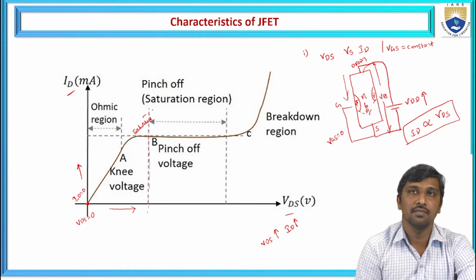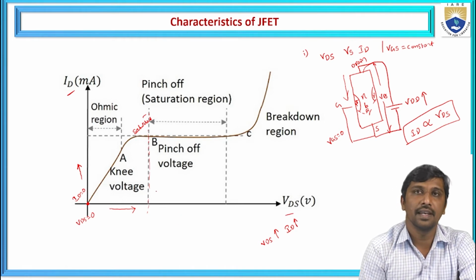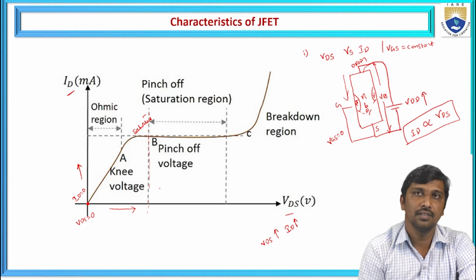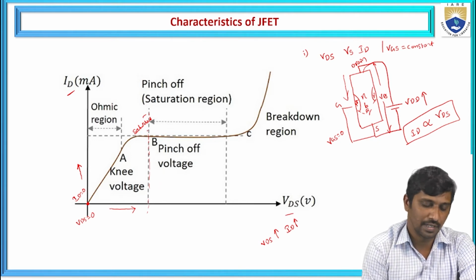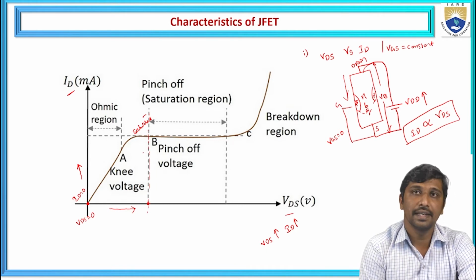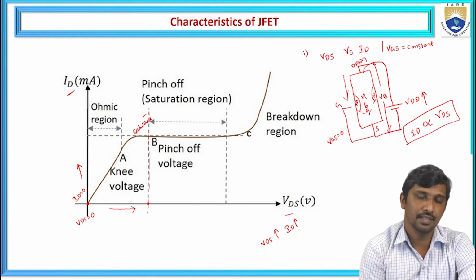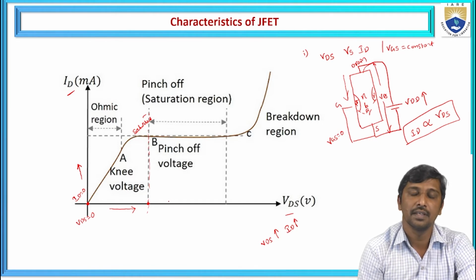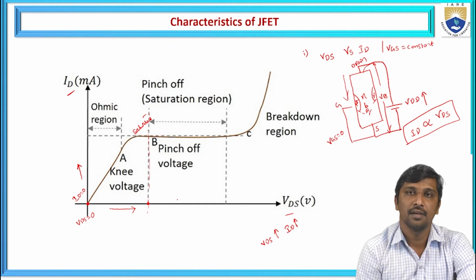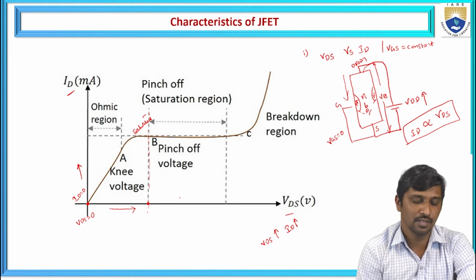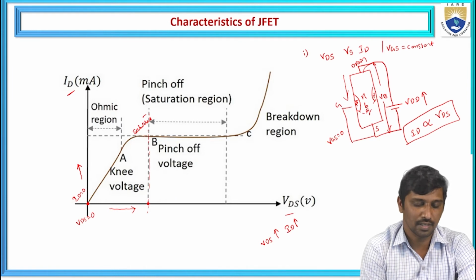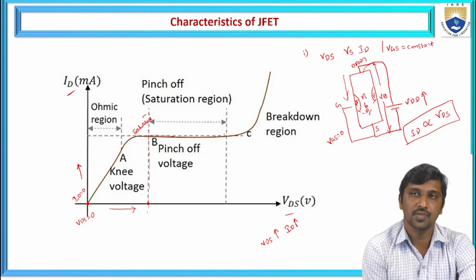That state means at which voltage the drain current becomes saturated or constant, and that voltage is called the pinch off voltage. Even though the biasing voltage between the drain and the source keeps changing, once the current is saturated, the current stays constant.